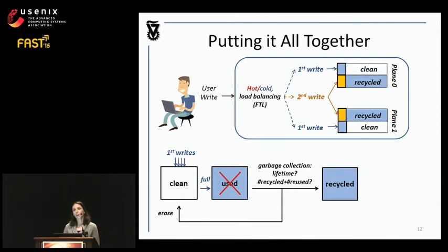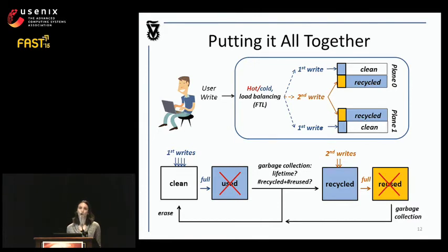But if the block is young enough, and if the number of reused and recycled blocks does not exceed twice the over-provisioned space, we can recycle the block, and then nothing happens. This is just a state change. Otherwise, we can erase the block, just like in a normal SSD, and again, nothing happens that's different from a normal SSD when a block is erased. Okay, if the block is recycled, it can now be used for second writes. So again, until it is full, once the data is invalid, then the block is chosen by the garbage collector, and now the block has to be erased.